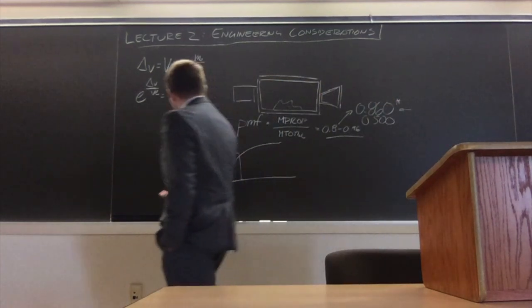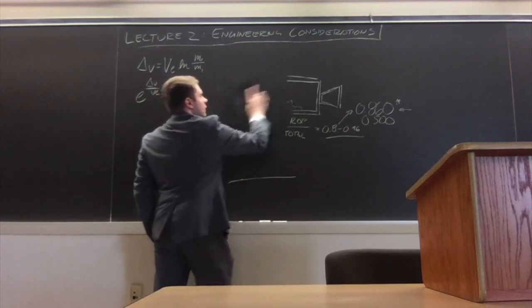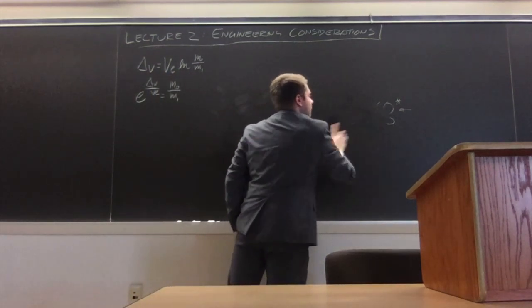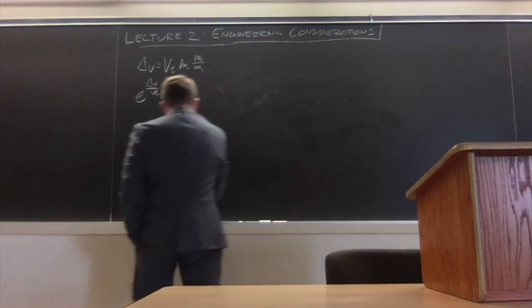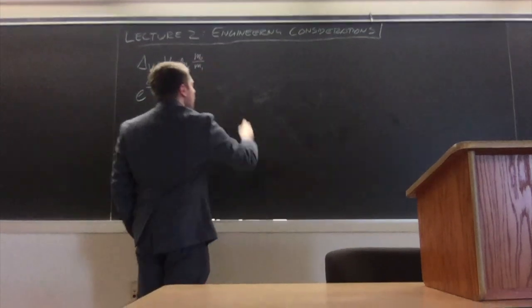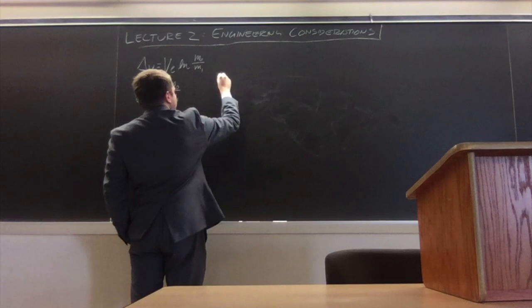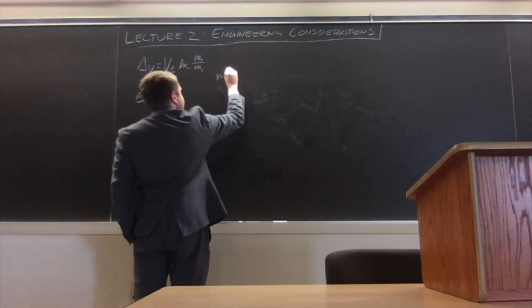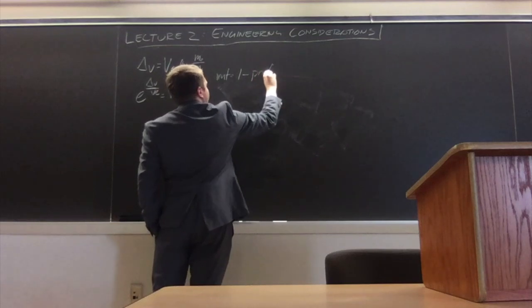So we have to account for this now in the rocket equation. And there are a couple clever ways we can deal with this, but I prefer the simplest, most straightforward way of doing it, which is simply looking at it from the perspective of the inert mass fraction, or IMF for short. And that's just 1 minus the propellant mass fraction.